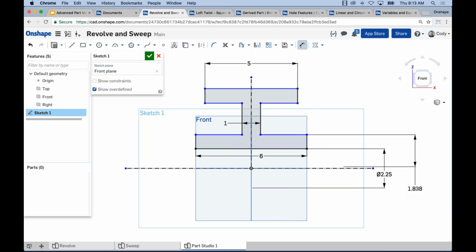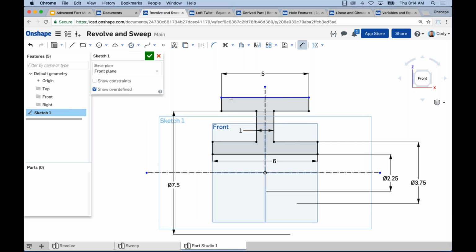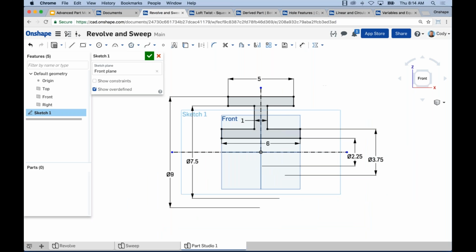Left click, and add that diameter dimension, right? Keep in mind that it's really useful for really understanding the design intent. If I had to dimension this in radius values, it would just look odd. It's not that I couldn't figure out what's going on, but it just would make less sense, right? Less practical. So here I've gone through and I've defined everything in the sketch, right?